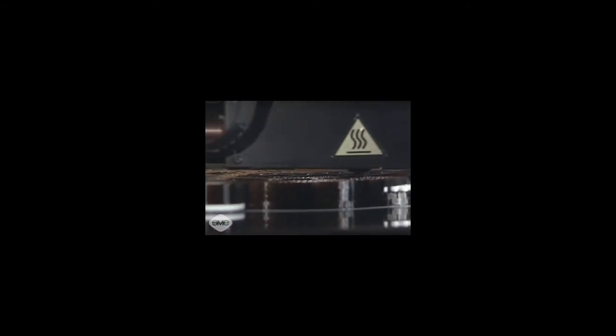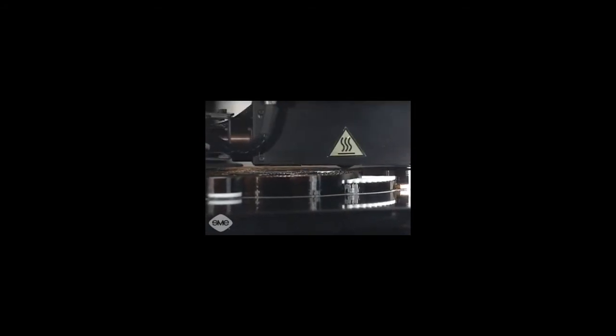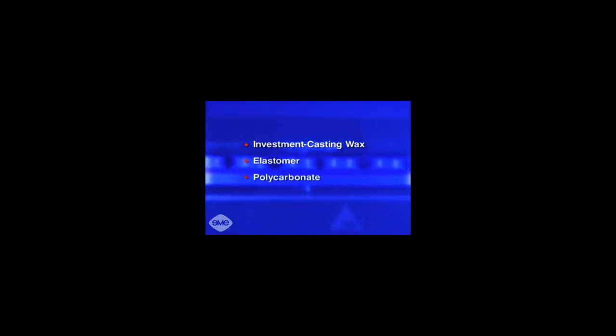As it is deposited, the molten thermoplastic material is just slightly above its melting point. Solidification occurs immediately after extrusion, as the material cold welds to previous layers. The most common material used for fused deposition modeling is acrylonitrile butadiene styrene, or ABS thermoplastic, in various colors. ABS provides tensile strengths of up to 5,400 pounds per square inch. Other materials used include investment casting wax, elastomer, polycarbonate, and polyphenylsulfone.